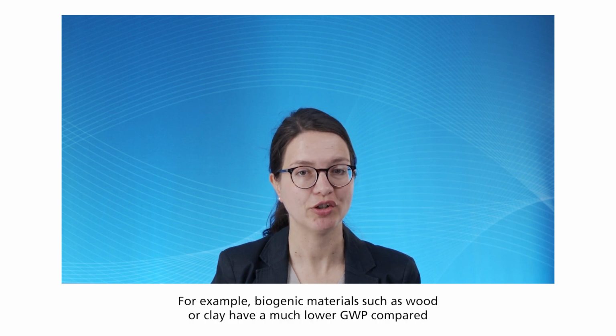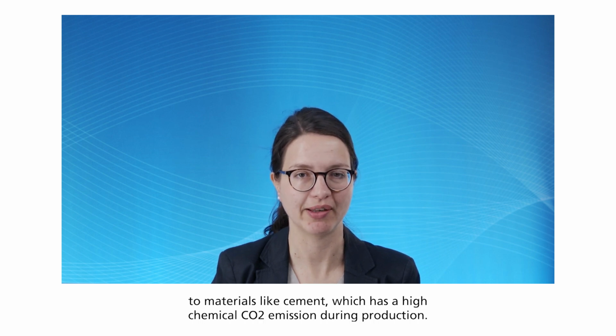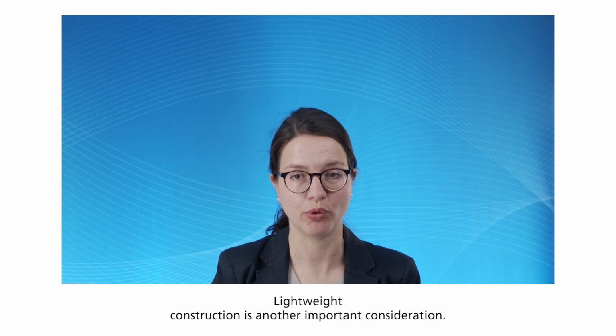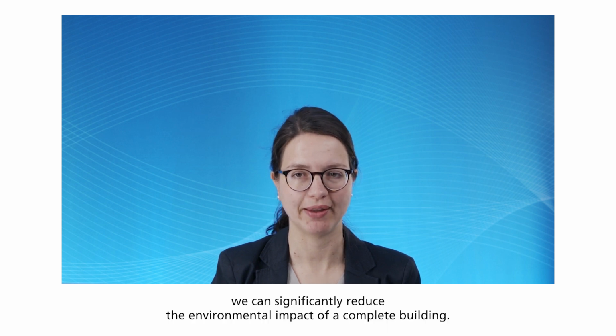For example, biogenic materials such as wood or clay have a much lower global warming potential compared to materials like cement, which has a high chemical CO2 emission during production. Lightweight construction is another important consideration. By using lighter materials and more resource-efficient construction methods, we can significantly reduce the environmental impact of a complete building.